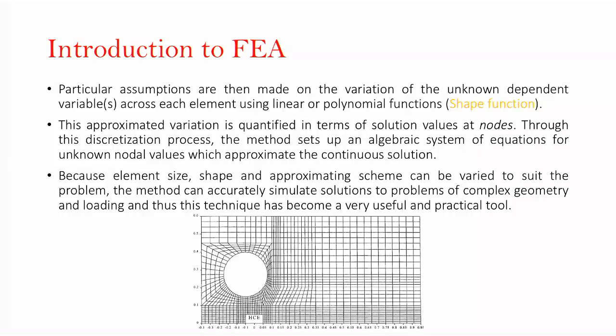But when we go for very fine elements, like small elements, we increase the accuracy. However, we increase the computational cost. So this is a trade-off here. It totally depends on our engineering judgment whether we want to go for small elements or big elements. Should we sacrifice the accuracy, or should we increase the speed of solving? It all depends on the situation and the physics of the problem that we want to analyze.